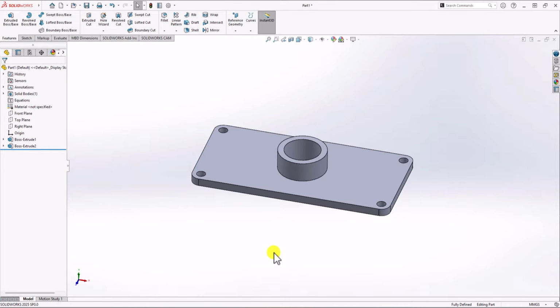Last step is to make the ribs. If you look at the question, you can see that there is a hint in the question. They're saying to start ribs inside cylinder wall. Basically, the expectation here is that you make a rectangle inside the wall, extrude that, and then cut it to make it like a rib shape.